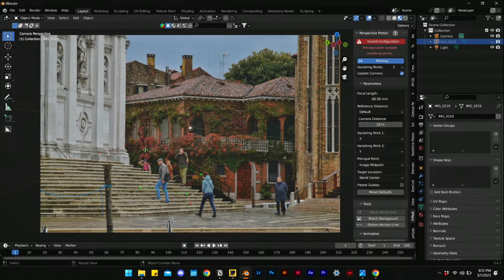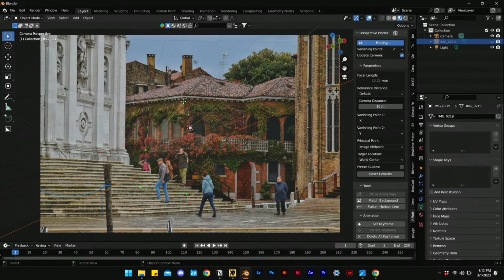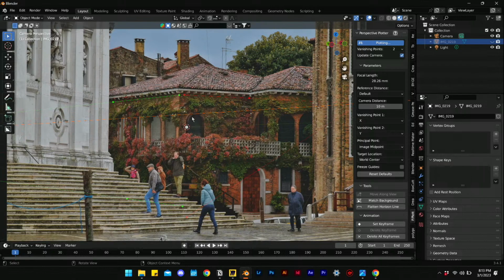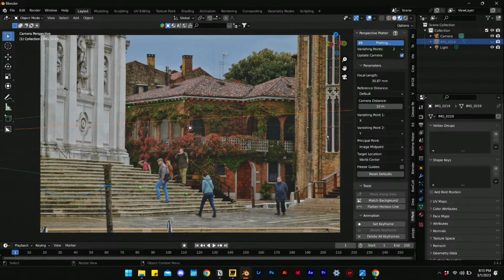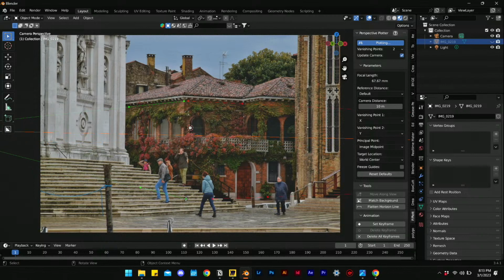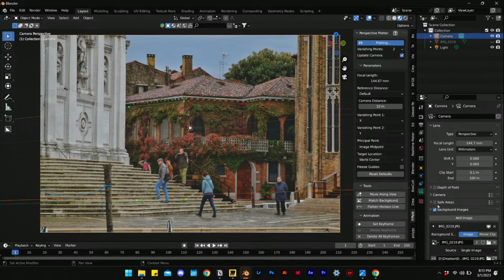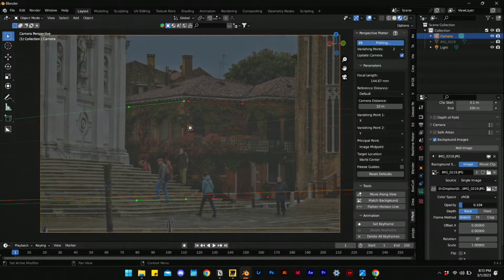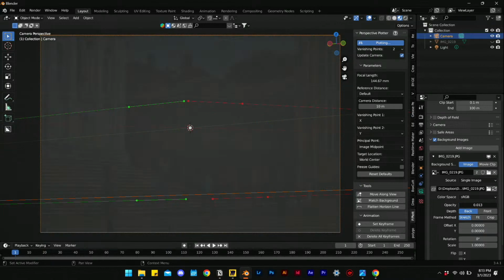This is actually the ground plane one, it seems. The ground plane can move later. I'll just worry about lining up these lines to the edges of this building and then doing the same thing for the red. And it's better to use the same height angle right there. If I lower the opacity of the image real quick, as I fix my perspective over here a little bit, select the camera, go over here, and under opacity, let's turn that down. We see there we have the 2 sets of lines, and then this white dot over here actually sets our ground plane.